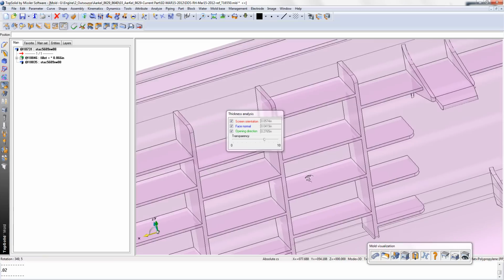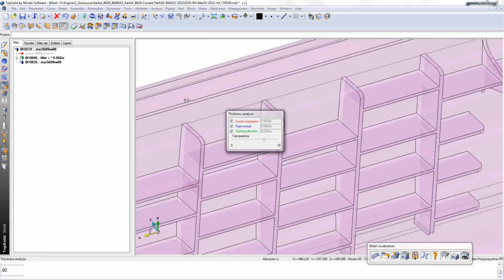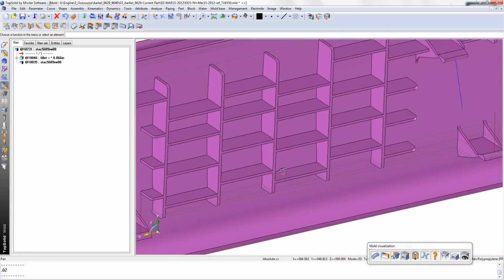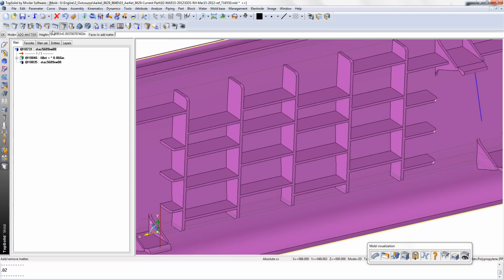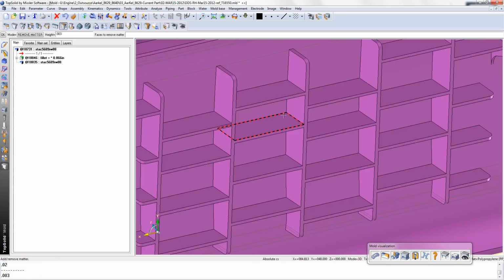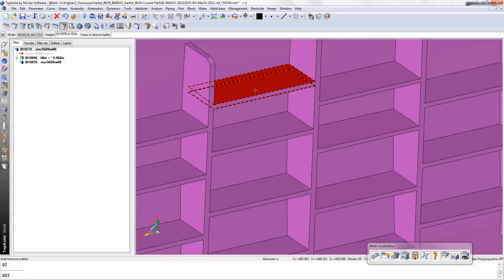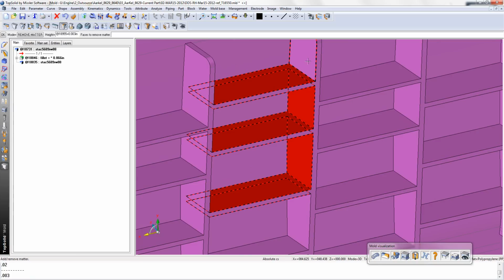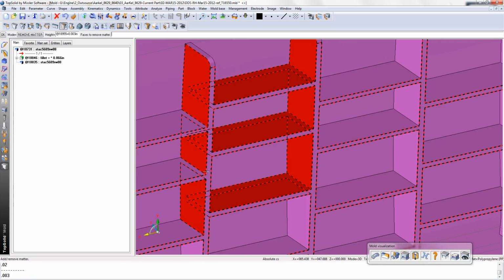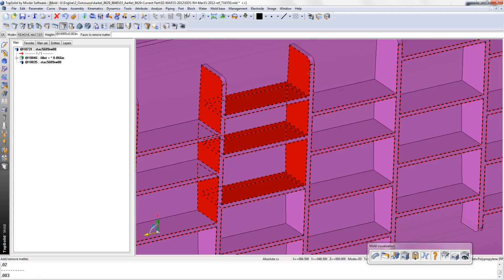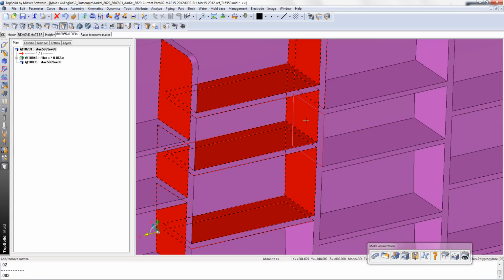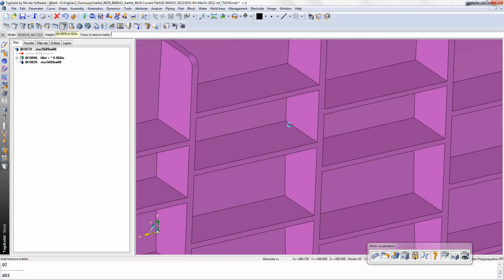For demonstration, I'll take more off so you can visually see it on the screen. Let's just go ahead and do that. While we're in this view, I have an add and remove function here, and I'll go in and remove 3 thou, and I'll pick this side as well as the opposite sides. And maybe even these faces here. I know I'm not picking the other sides, but this is just to show you. Say okay, and that'll bump those walls over.